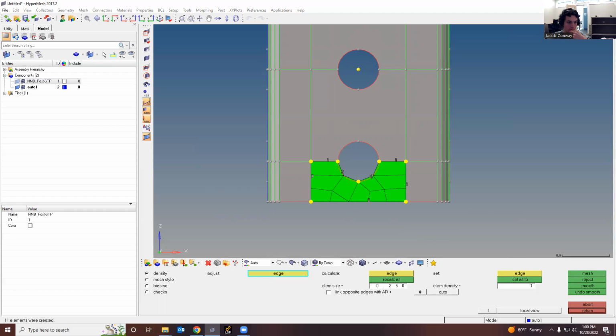Again, I got this to work very easily with a 0.5 size mesh. However, obviously this is looking a little bit more precarious than that was. So I'm going to just be playing around with these by right-clicking and left-clicking these numbers. I can change how many nodes intersect at this edge. So this looks fairly good. I don't like that little slant. I don't really know why that's showing up.